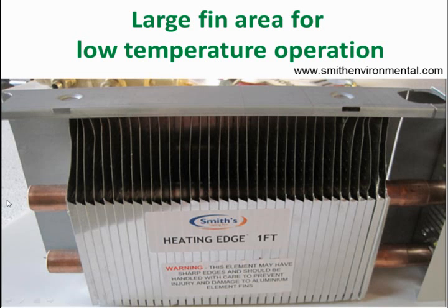What's neat about this product, it can be fed a couple different ways. You could feed both those together, or you could go down one with the supply and return back through the other, and it does change the output depending on how you choose to configure the piping on that. But it's a nice-looking element. It's got a nice enclosure to it, so check into that. They do show some outputs at very low temperatures. I think their temperatures are going down to about 100-degree average supply temperature with their output charts.